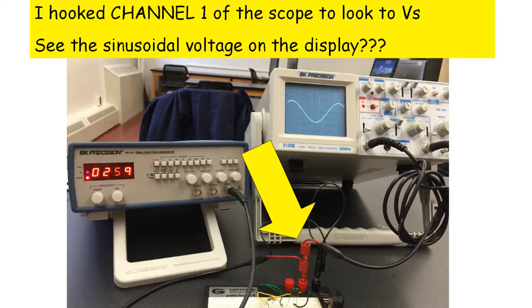Okay, I hooked channel 1 up to the source voltage. You don't have to do this, but it's right on top of here. It's not going through here; it's the lead coming out of this guy, and I've got it right on top of the lead coming out of the AC power source. The ground of the oscilloscope is hooked into this ground. So this oscilloscope is hooked directly to the output of the AC generator, just like you had in the last exciting multisim demonstration.